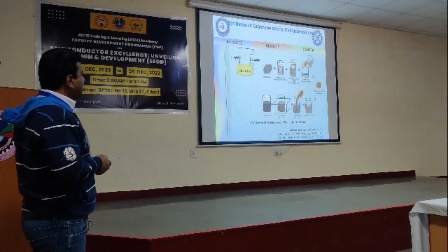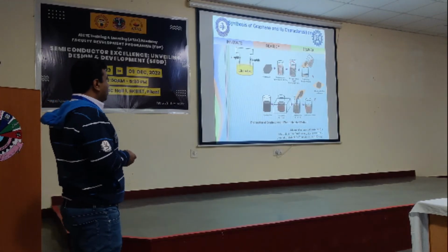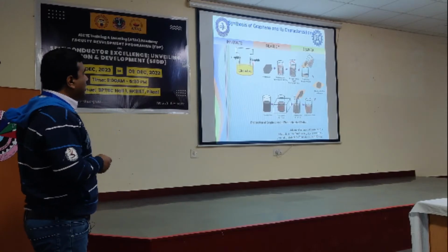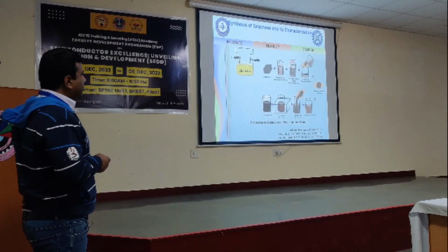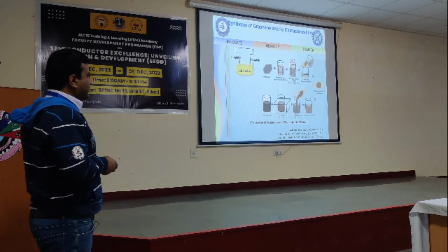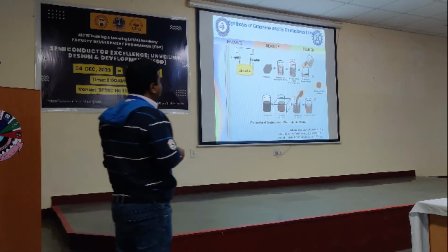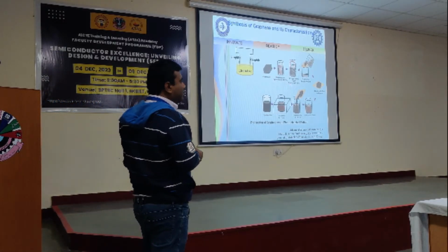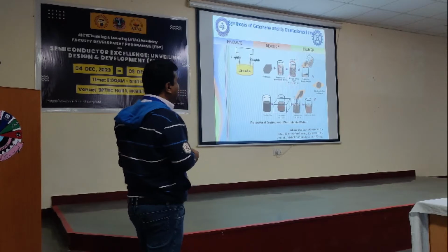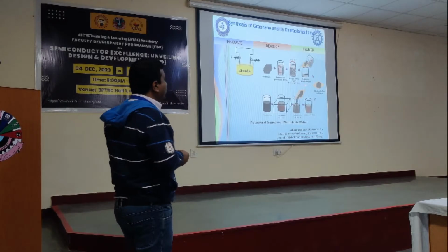Now this is another chapter I have to do, that is synthesis of graphene based flexible devices. Now this is all derived from graphite flakes. This is preparation of graphene by the electrochemical exfoliation technique. See, graphite flakes are dipped into the electrolyte solution, then a voltage potential is applied, and the graphite flakes turn onto your filter paper.